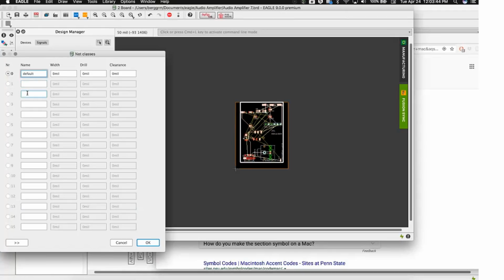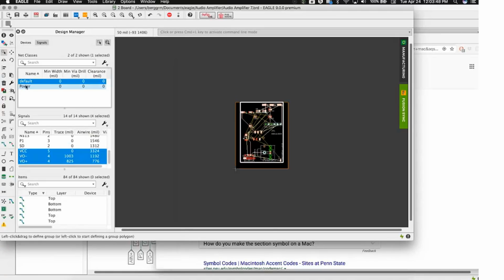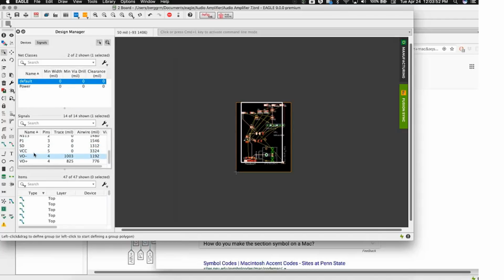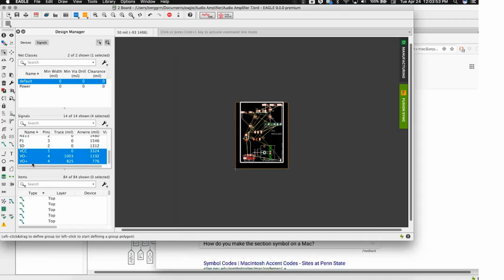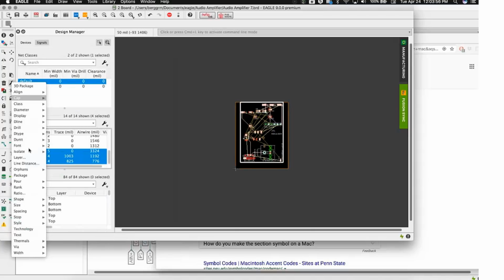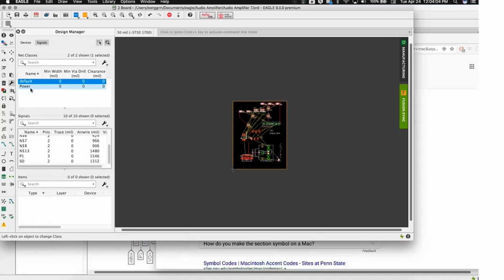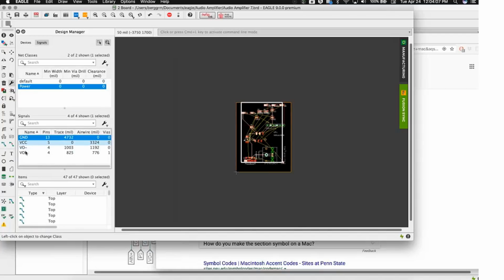They're both defining minimums. That's why whenever we see a user modify the default net class, we cringe, because the idea of the default net class is to stay at all zeros. That way all the minimums specified in DRC are winning. So the DRC is in control of the default net class. The moment you start to tamper with the default net class, now you could potentially be overriding DRC.